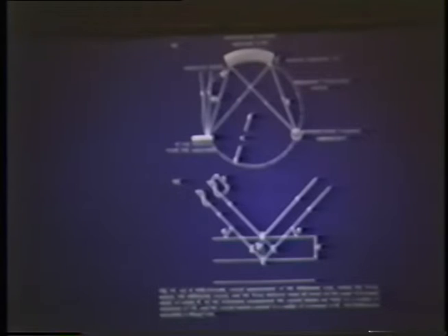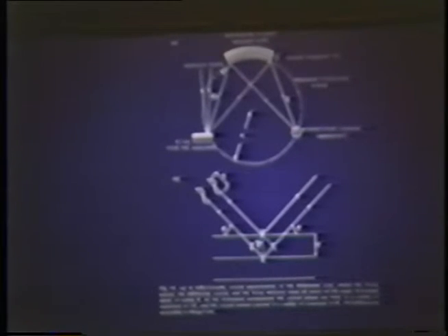The peak to background ratio is much higher in wavelength detecting systems, which improves the limits of detection. And certainly the light elements down to Z equals 4 are much more easily detected. However, these advantages must be set against a number of limitations. The overall efficiency of collection, i.e. the proportion of X-rays measured to the X-rays emitted, is low. Now, this may be improved either by increasing the beam current, which has the problem of damaging the samples, or increasing the probe diameter, which will decrease the spatial resolution. There are long analysis times, typically between 30 and 60 minutes, which too can result in damage to the specimen.